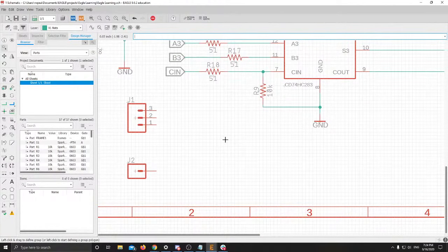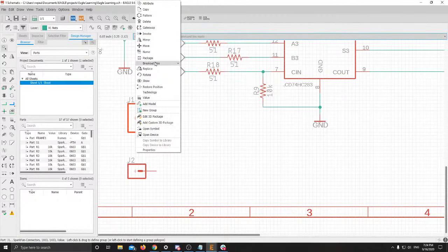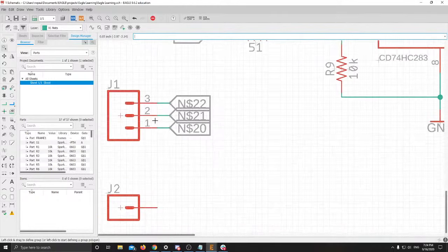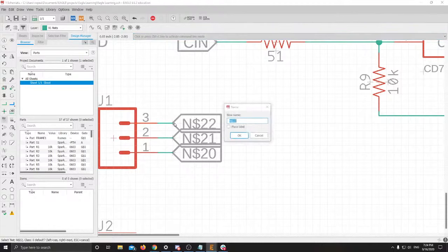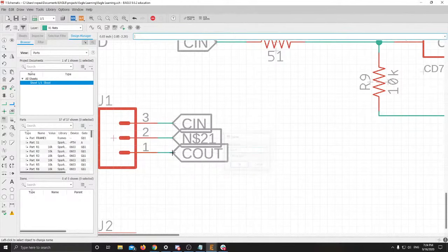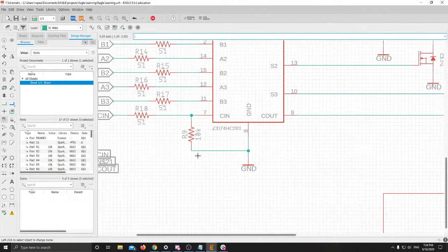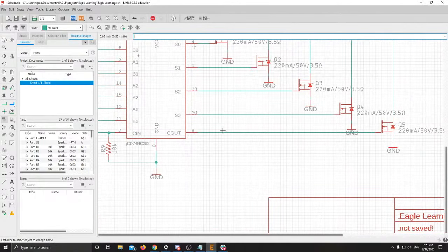All right, so this is where we can use that trick that Justin mentioned earlier. If I right-click on this, I go to Breakout Pins, All Pins, Default, and then we'll get these 3 little breakouts. So again, this one I'm going to name Carry-In, or C in. That'll connect it to the one we made earlier. This one I'm going to name C out. You'll notice that isn't going to connect to anything. It's because we haven't named this net.